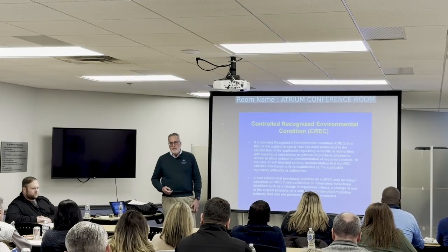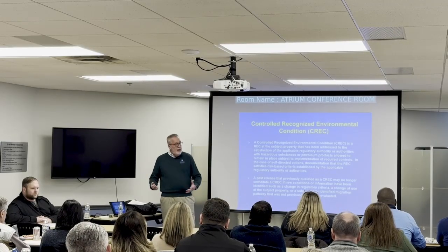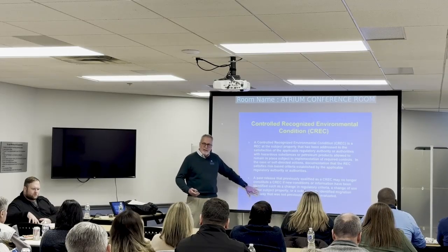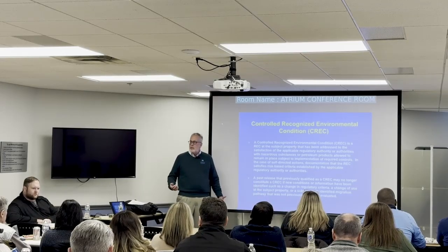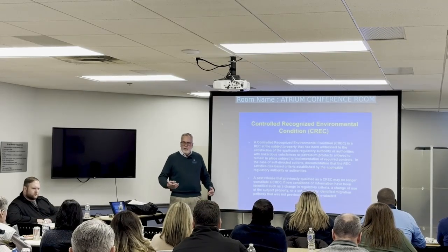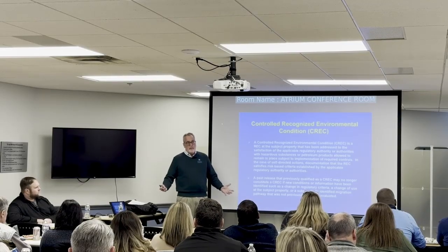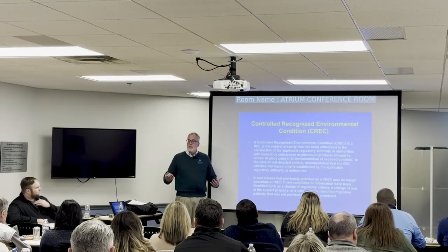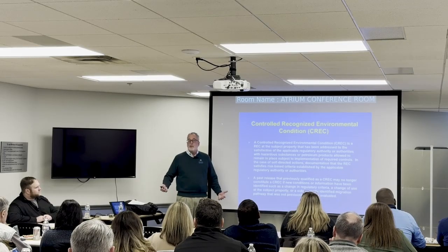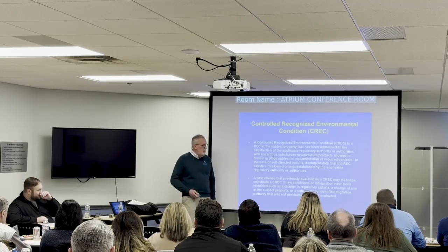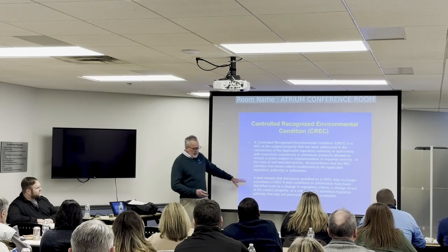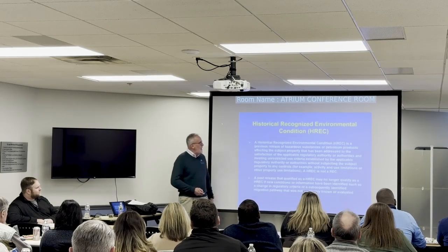Even the voluntary action program wasn't. So there's VAP sites that had NFAs through the Ohio EPA that really didn't address that vapor intrusion exposure pathway, which if you look at this building, we're not going to be exposed to the soil, we're not drinking the groundwater. If there's a significant problem with this property, it's going to be vapor intrusion into the building, potentially, if you've got volatile contaminants that are beneath the building. So that kind of throws a wrench into the CREC.